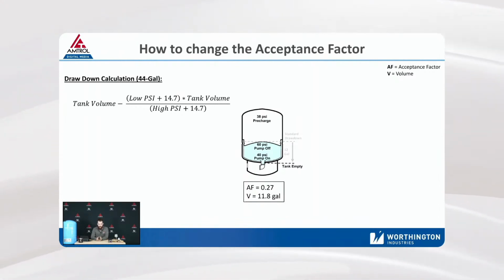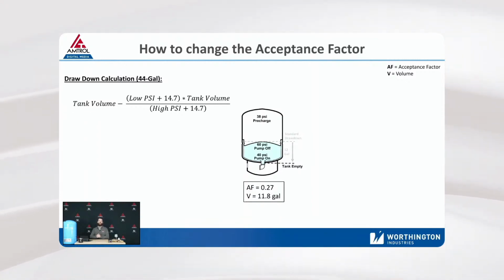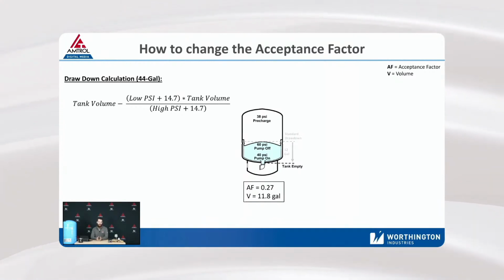Before I even go into this, one thing I want to note with supplemental drawdown, and I know I mentioned it in part 1 as well, I think it was one of the questions we got: is this something that's good for the tank, or does it make the tank work harder? So we dove into it a little bit, I thought about it, and the answer is yes. It's not something you want to do all the time if you can avoid it. There's a reason why we recommend 2 pounds below your cut-in. That's for a reason, because that's where the tanks are meant to be operating. That's their sweet spot, if you will.